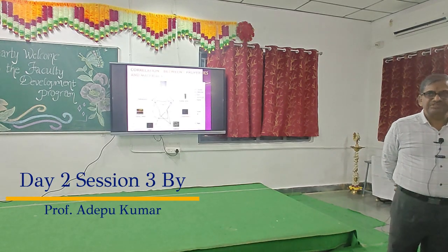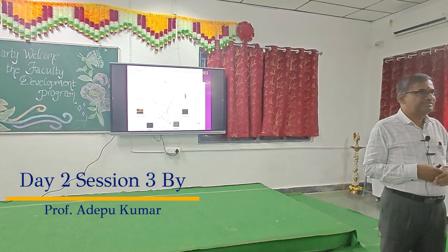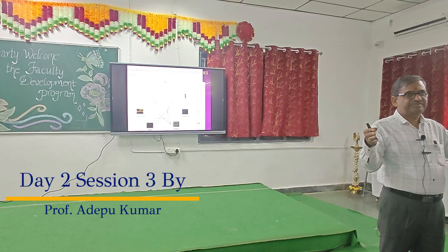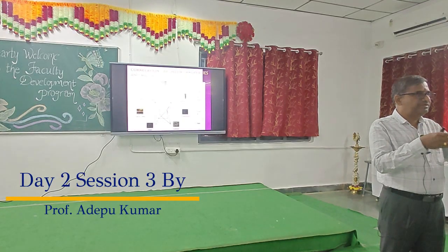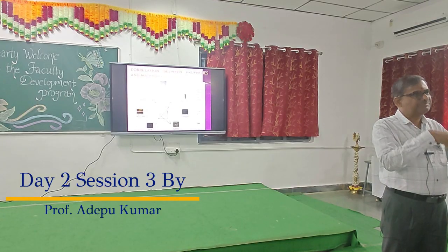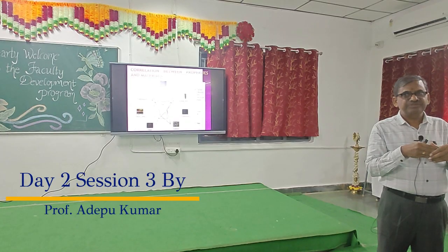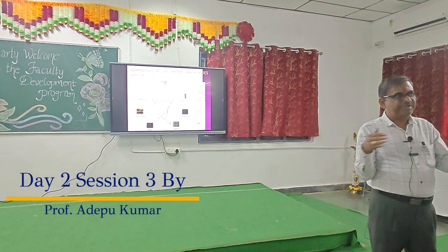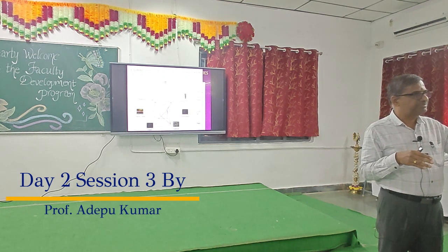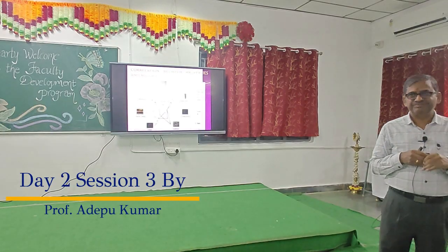So to reduce porosity, how does the porosity come into the picture? You need to know that. So once you are welding in an open atmosphere, that metal is melted, the gases surrounding you are absorbed by that liquid metal. Okay, so once you are doing welding or printing of the material using the WAAM process in open atmosphere, you may get porosity. That is the reason.